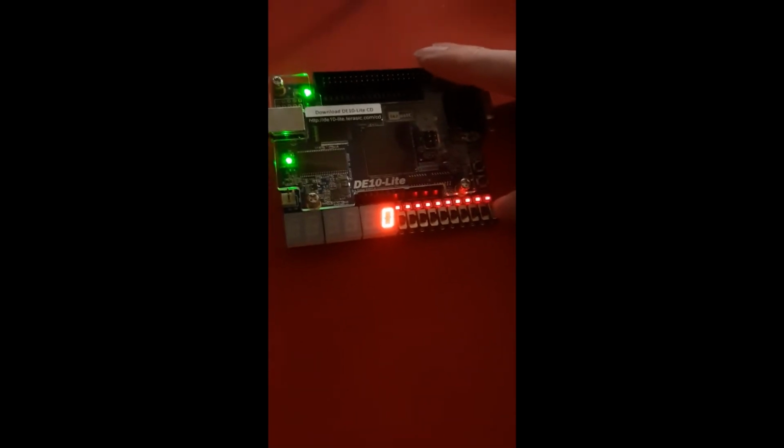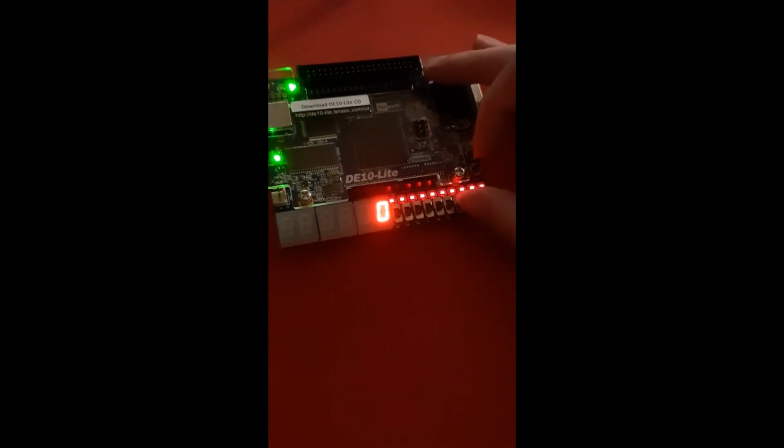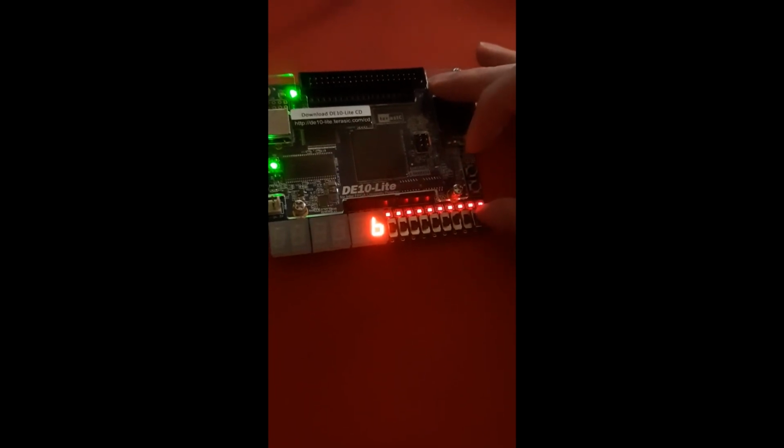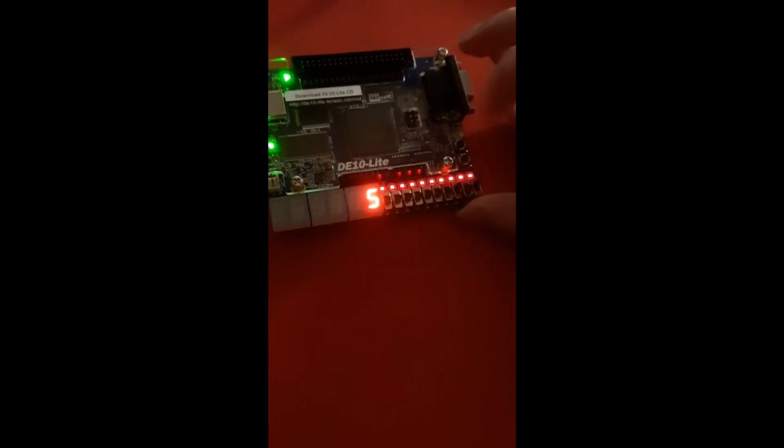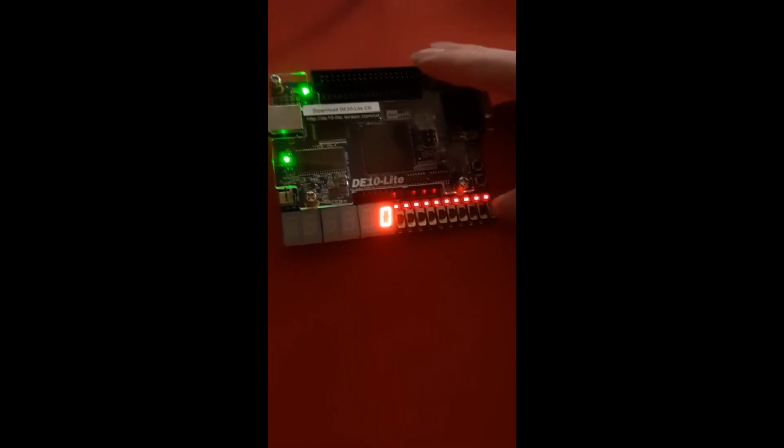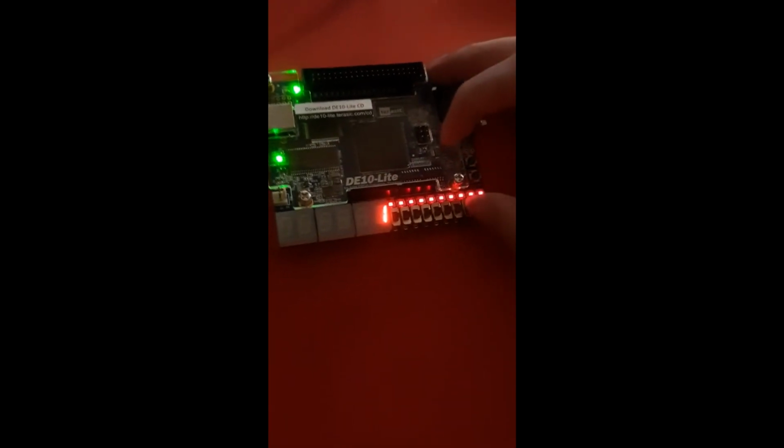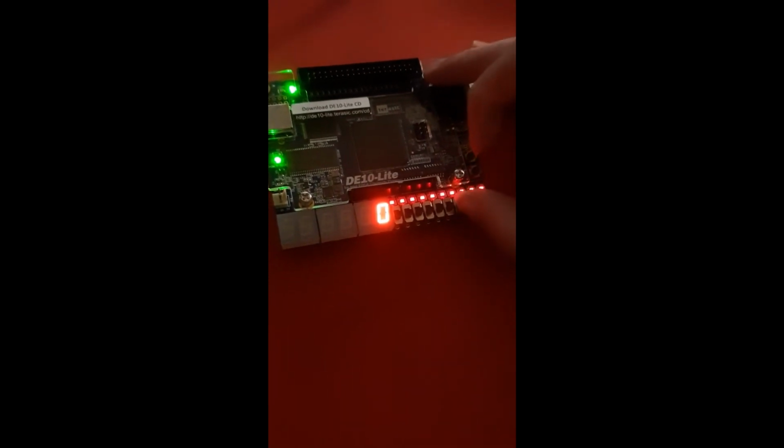Step number 5, testing your design on the FPGA board. In this example, you may now notice that if we toggle the 4 switches, the value of the 7-segment display changes. If the switch is up, it represents a 1, and if the switch is down, it represents a 0. Depending on the corresponding 4-bit number, it will now be shown in decimal on the 7-segment display. The design works and is a success, so we know that the hardware has been successfully synthesized and implemented.